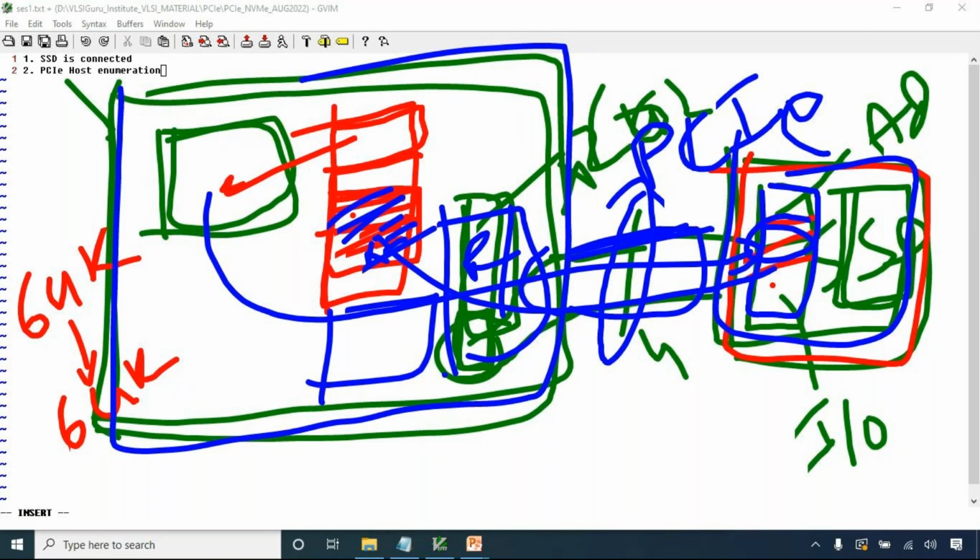But I'm understanding it's the main controller which sits in the SSD. Yes, exactly, it's the main controller. You have PCIe as hardwired signals and link, but you use NVMe technology to communicate over PCIe. Moreover, does it work as a DMA controller? Yes, the NVMe controller is more like a DMA controller. So there's no internal DMA within the host? Host won't require DMA in this case.